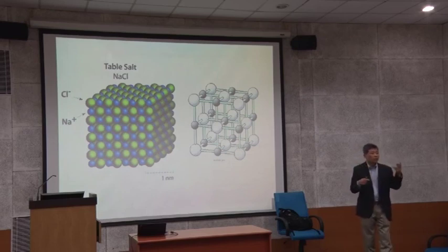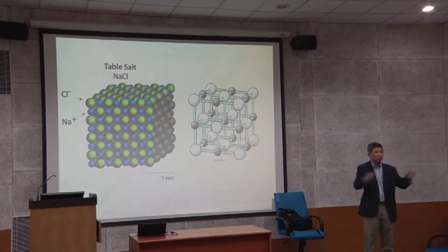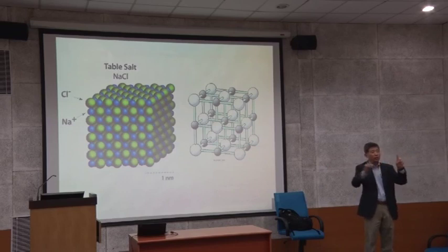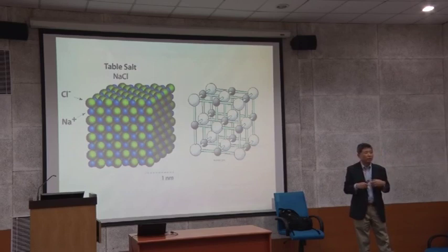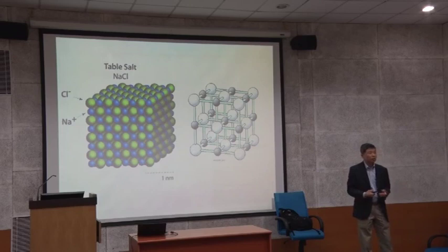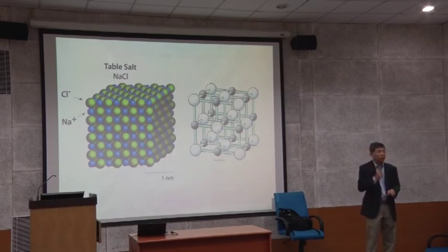And then your X-ray diffraction has two pieces of information. When you scan your X-ray in powder diffraction, what do you get? First, angular information, right? Intensity versus 2 theta angle. And you have a lot of peaks. But the peak position in X-ray diffraction tells what kind of shape of unit cell. Okay, basically, the shape of the unit cell is its length or angle. That's what you get from most X-ray diffraction. But your intensity information tells what kind of atoms and their specific locations.